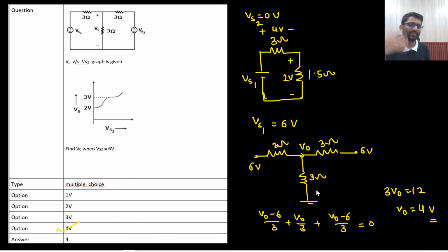Or you can apply the concept of half circuit here as well, right? Concept of half circuit. Just to make the problem complex. This will be replaced with 6 ohm. 6 ohm and 6 ohm in parallel. Then you apply the concept of half circuit. Both are positive. Then it will be open-ended. Not shorted. It will be open-ended.